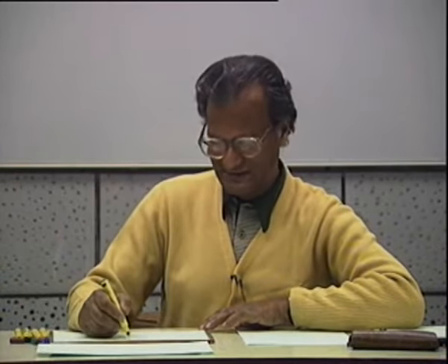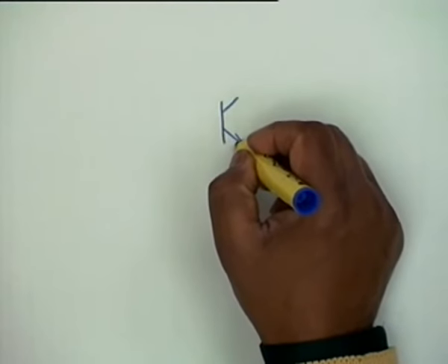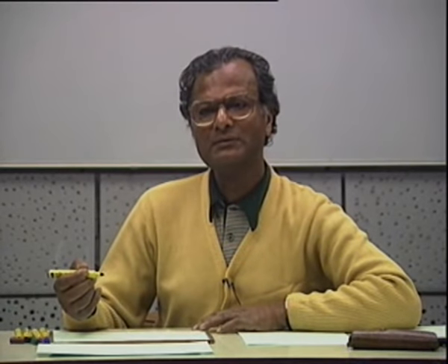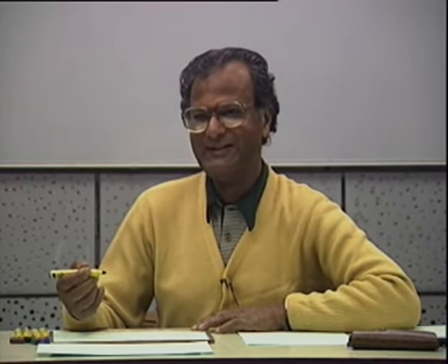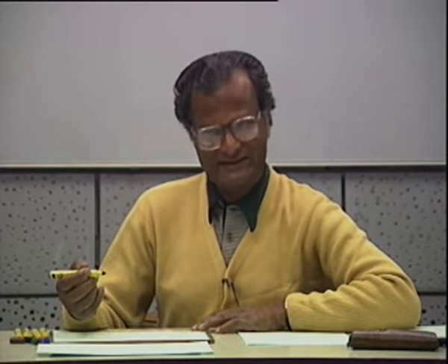Excuse me, sir? Yes. In this case, will the two transistors have a VCE of 15 volts across them? Because it's 15 and 15, 30 volts. So each one will have 15 volts VCE. Can they stand it? They have to. You have to design such that they stand it, yes. If VCC is plus 15, in fact the transistor should be able to stand 30 volts.